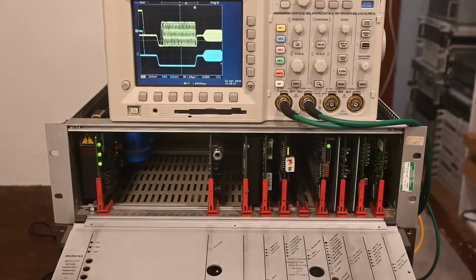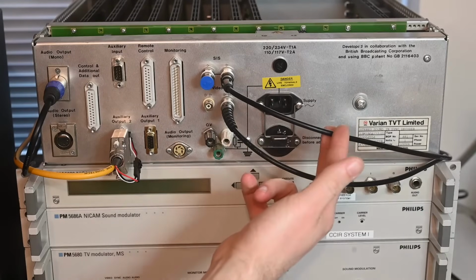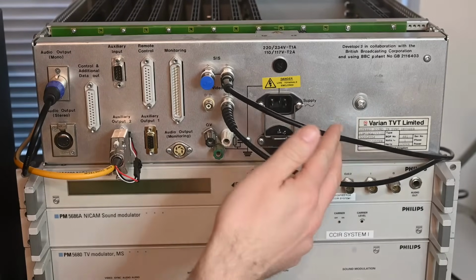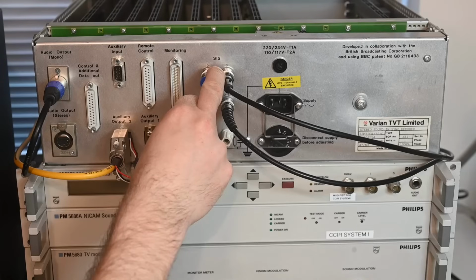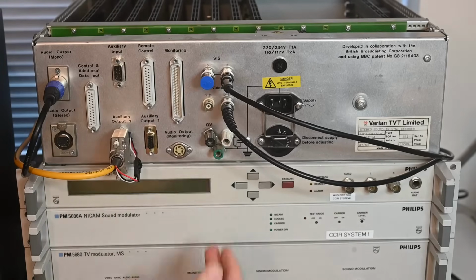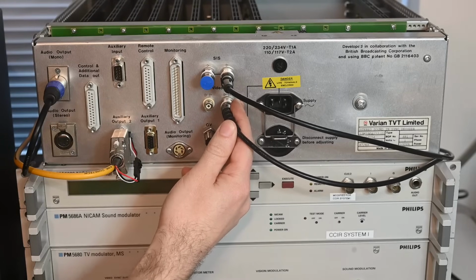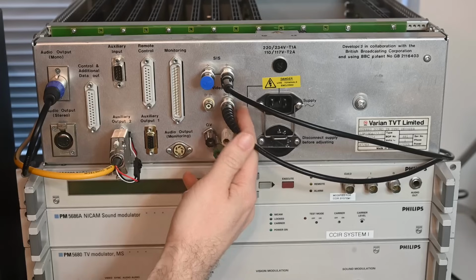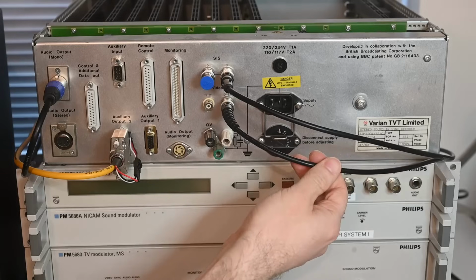For our rear view, we're going to focus our attention on the SIS decoder because of course that is the main equipment of interest here. Now this cable here is coming from our Pretend Studio, and that of course is the SIS data burst and video, and that's heading into the input here. And this is a high impedance interface once again, which has to be terminated with that 75 ohm termination. And this connection here is the video output, and this is basically the recovered video. So the SIS burst has been stripped out, and this has been returned back to a normal sync, and that heads on to the vision modulator.